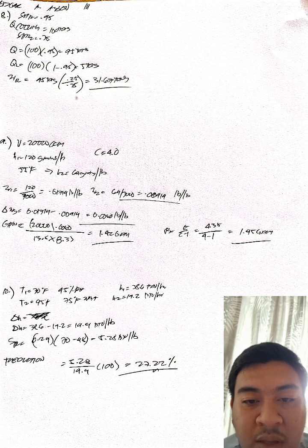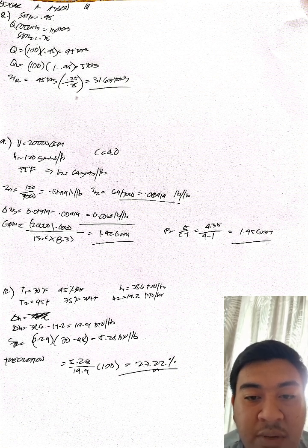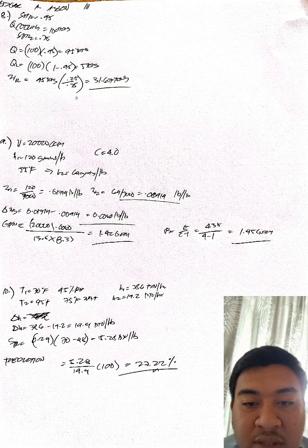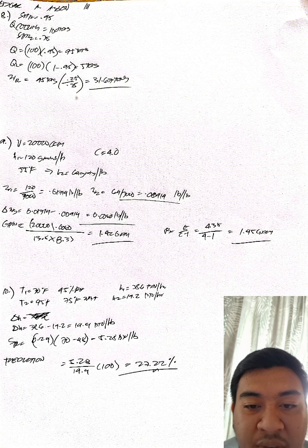For the latent heat, the 100 ton load is multiplied by 1 minus 0.95, and we have the answer of 5 tons. Now, if we substitute this with the system running at 0.75 sensible heat ratio, it will remove far too much moisture, causing over-dehumidification. To find the extra dehumidification load required to restore the room to 50% relative humidity, we take our sensible capacity and look at the ratio discrepancy. My calculation shows that the extra dehumidification load required is 45 tons, multiply the difference, and then the final load is 31.67 tons.